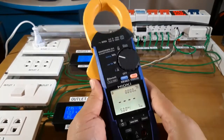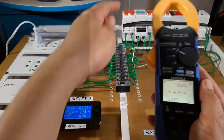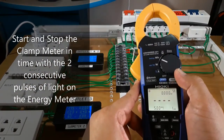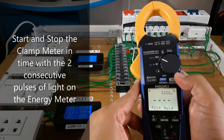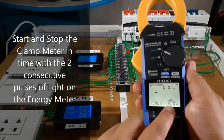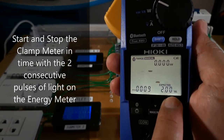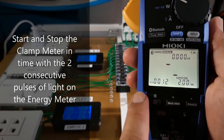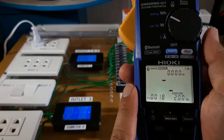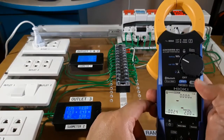Now suppose I have already set up this instrument and I'm ready to begin synchronizing the measurement of this meter with that other meter. The moment the light of that meter flashes, I'm going to press the hold button, which means to start the measurement. And immediately we will see the 2 watt-hour expected measurement value. This value here is the time elapsed, and rotating lines mean that the instrument is gathering data. So to stop the measurement, we wait for the next pulse of that meter